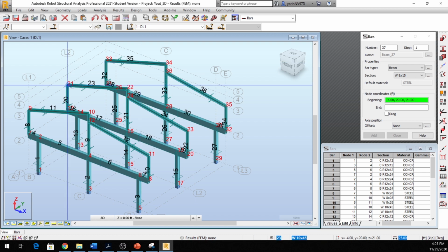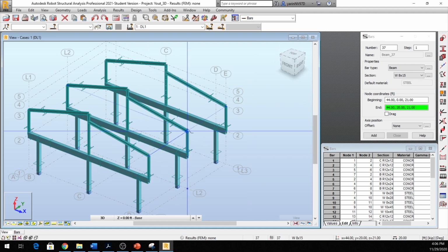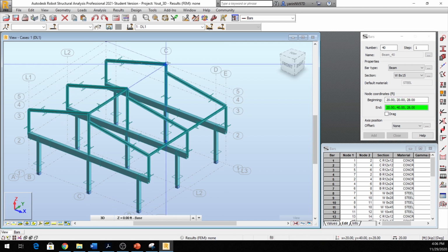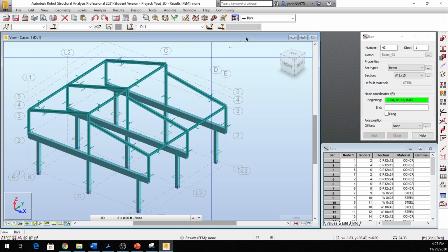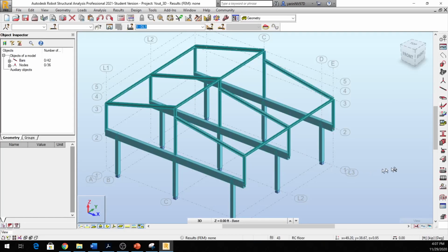So now what we're going to do here, let me close all these out. I'm going to go ahead and do our bracing right here. Put one right here and put another one here. Come back on top. Two. There it is. I've done the lateral bracing. Let's go up here and go back to geometry mode. And it should look like this.